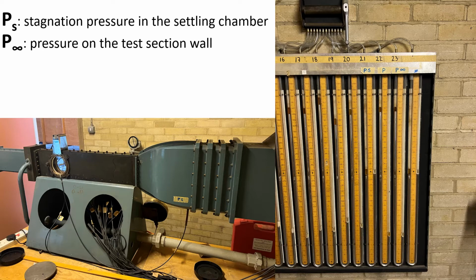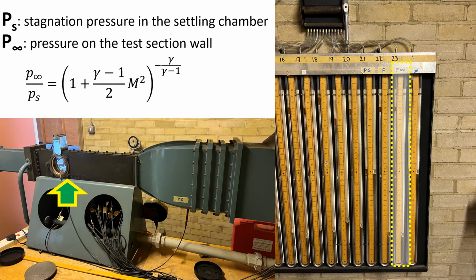And also we have P infinity, which is manometer number 23. So where is it? It's actually on the test section wall, lower wall. So it's manometer number 23. So knowing PS and P infinity, we can use this relation to get the Mach number. The design Mach number of the supersonic nozzle is Mach number 1.8. So through the measurement and doing this calculation, you can compare with a theoretical design value whether there is a discrepancy.